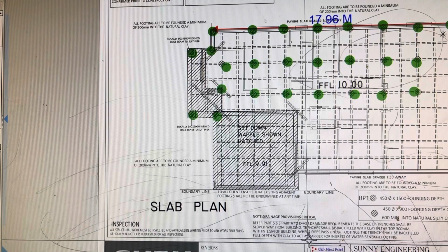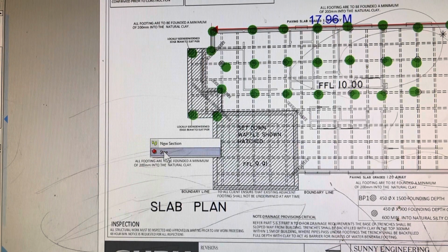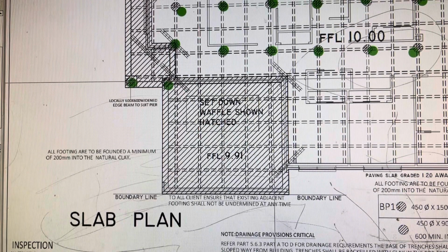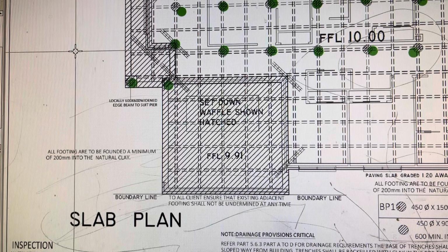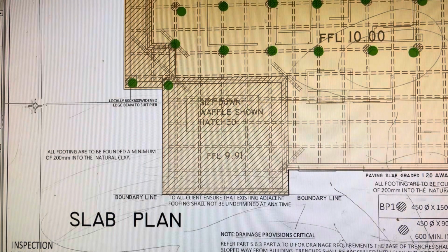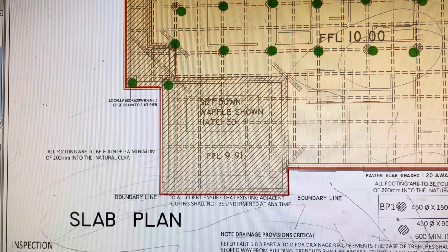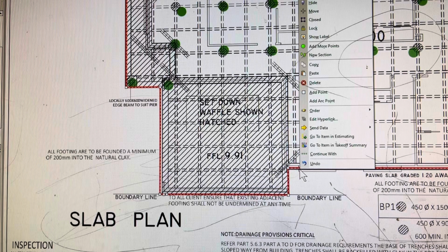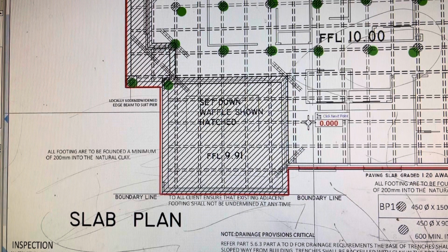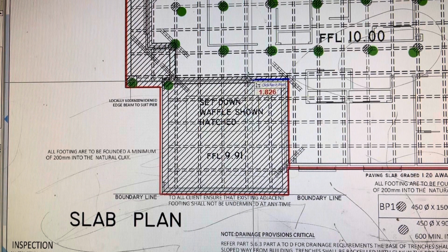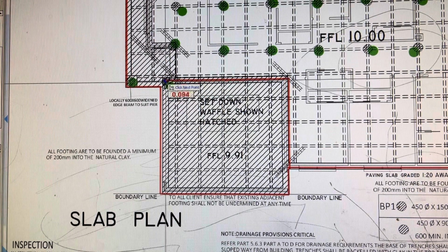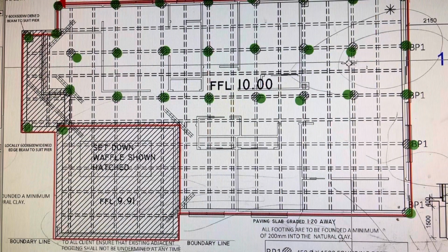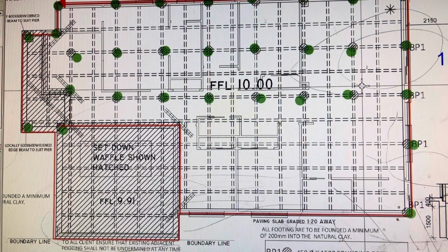Now we got all the quantities which we need, most of them. We have to take this stem or this edge. We will put this in edge beam because it's a big beam. So we can just click and click new section for this edge beam. We can just add to this existing edge beam quantity. So now we got the complete quantities of the area of the slab, internal, external edge beams, bored piers.